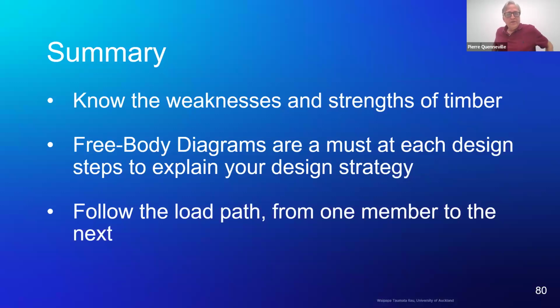So, to conclude and summarize, one needs to know the weaknesses and strengths of timber. Weaknesses: compression perpendicular to grain, tension perpendicular to grain, really. Free body diagrams, I repeat this, they are a must at each design step in order to explain the design strategy. And really the important thing, tell the students to follow the load path from one member to the next and through all the different components and through all the different loading actions.